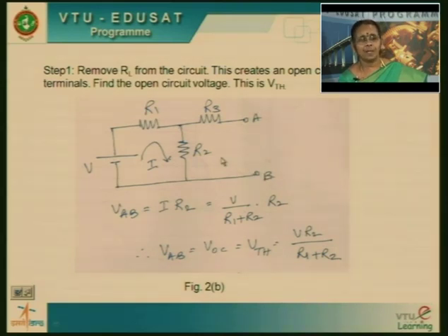The next step is to find the voltage across the terminals A and B. What is it equal to? We have to analyze how to find the voltage across A and B. Generally speaking, the drop across the resistance R2 and the drop across the resistance R3, the sum of these two should be the voltage across AB. But R3, if you just look at it, is in an open circuit. Since it's in the open circuit, no current flows through R3.